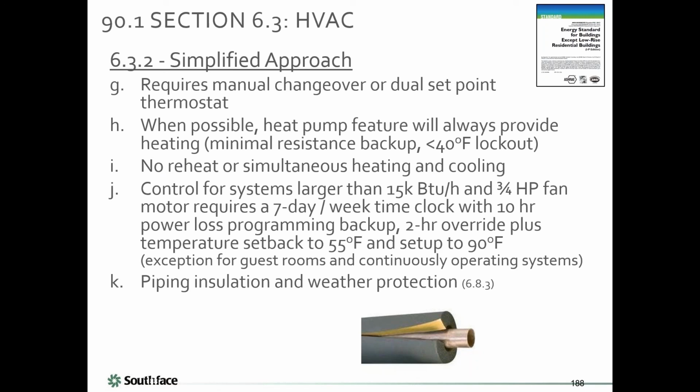They're also very big on shutting equipment off. So anything bigger than 15,000 BTUs, and Ali, that's like bigger than a motel. Motel room is probably the upper limit on that. So anything bigger than that, you've got to have a 7-day-a-week programmable thermostat. That's kind of where it's kicking in. That's typical, I guess I should say.